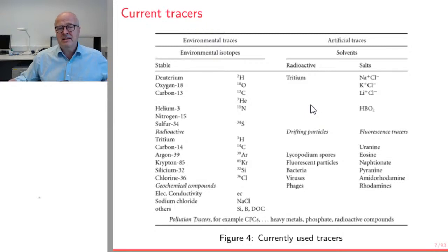So if we want to detect a signal from our tracer experiment, we have to have a response that is in the hundreds milligram range or even more. So we have a ratio injection to detection of 1 to 1,000. And this leads to scenarios where we need not just kilos, but sometimes tons of salt to actually create a result. This is why salts can only be used at very small scales.